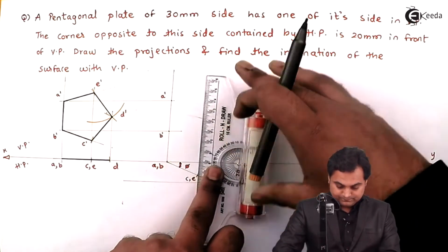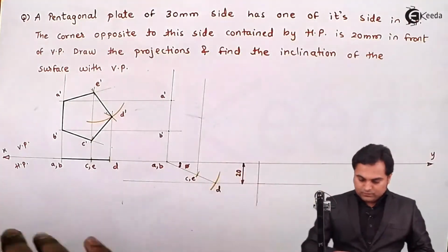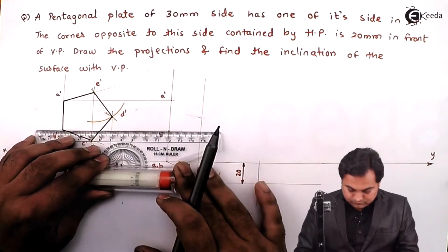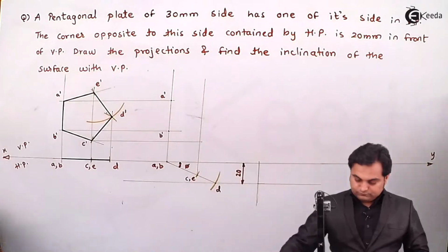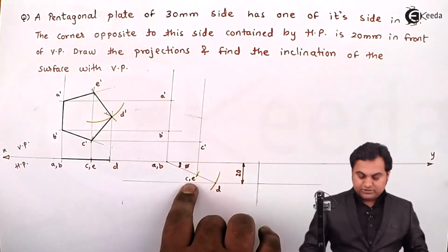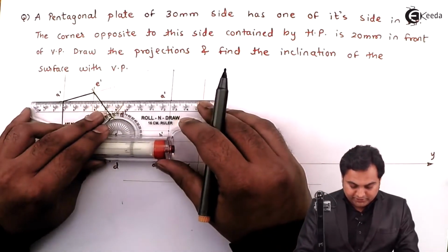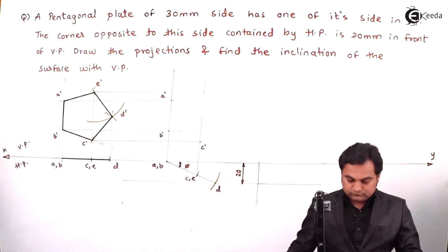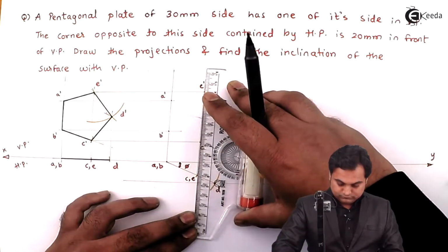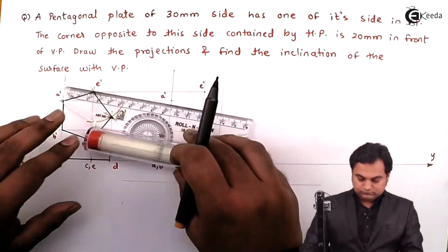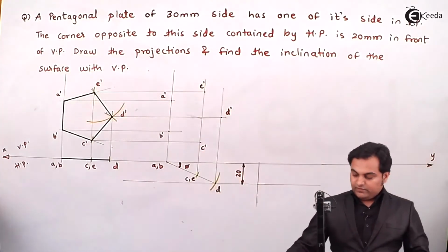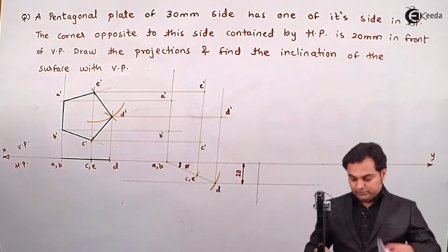projecting them upwards. So here projecting C and E, and from the front view getting C dash. So where they intersect, here I'll get the point C dash. On the same location there is point E as well, so for that I need to bring E dash here. Next, for point D, here we have point D dash. Next, joining them in order.